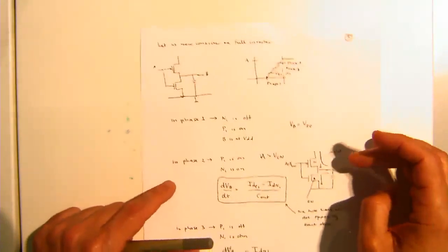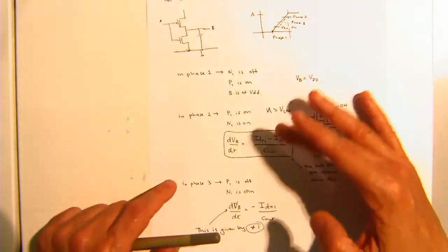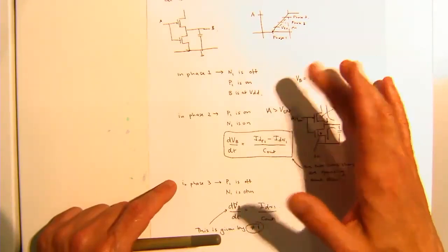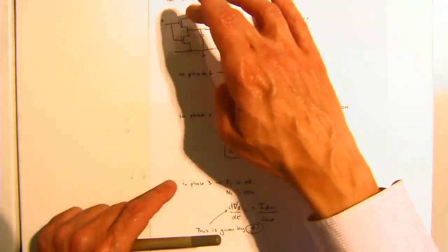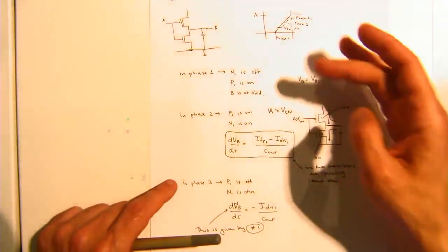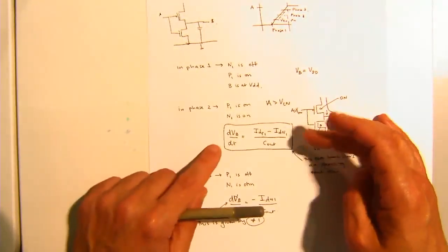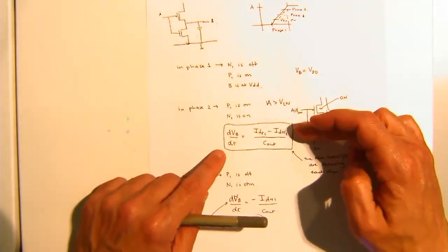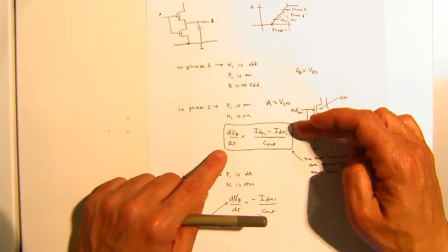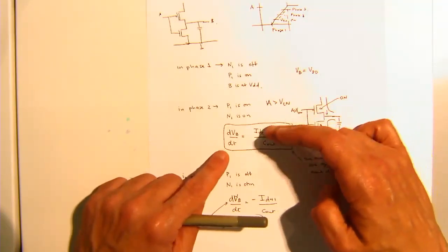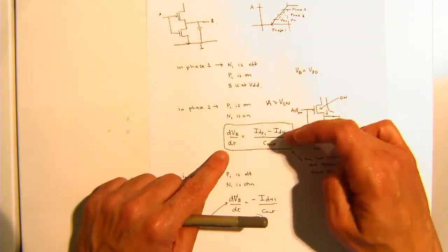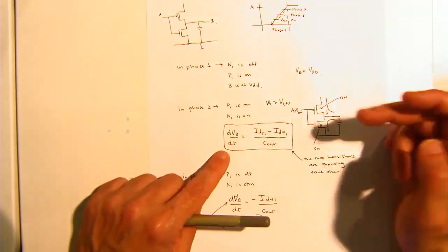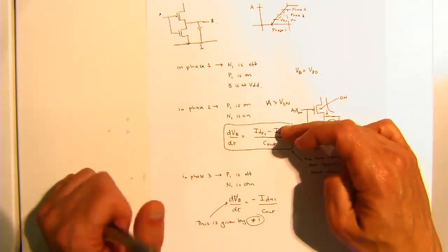And essentially what we showed is that this inverter goes through three stages. The first stage is when the NMOS is off and the PMOS is on. The next stage is when both the P and the NMOS transistors are on. And what we're seeing here is a situation where the P device is pushing current, whereas the N device is trying to sink current. So essentially they're fighting each other, so therefore we don't get as sharp a transition as we would desire.